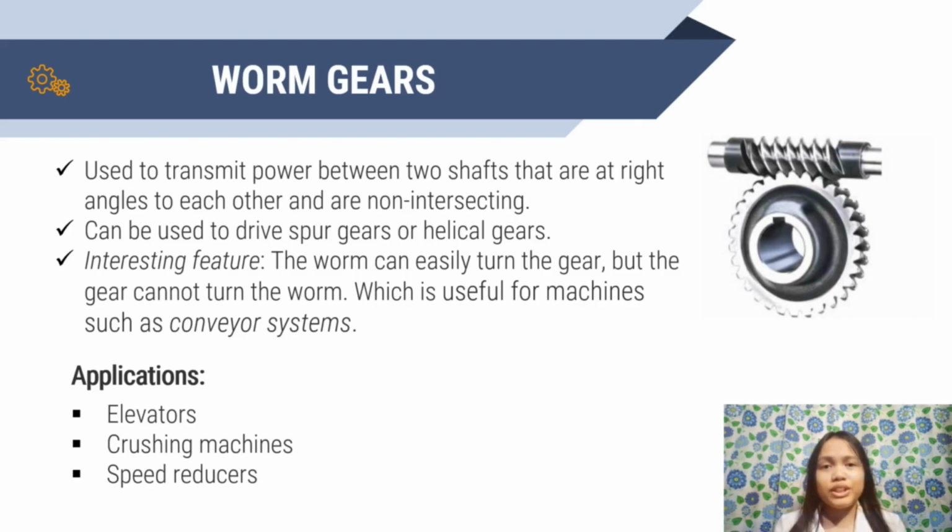Worm gear is always used as the input gear, and the torque is applied to the input end of the worm shaft by a driven sprocket or electric motor. But worm gears yield low efficiency because of high sliding velocities across the teeth, thereby causing high friction losses.